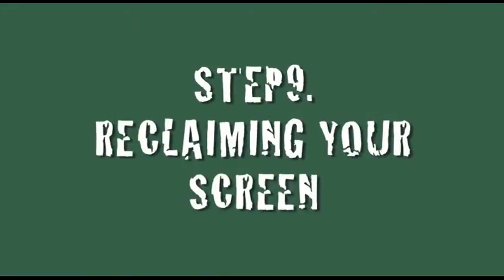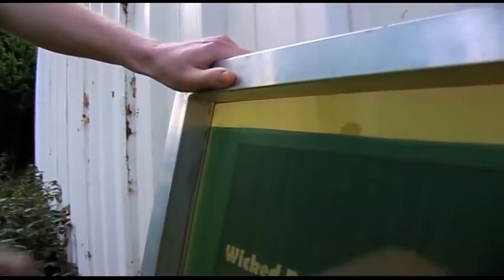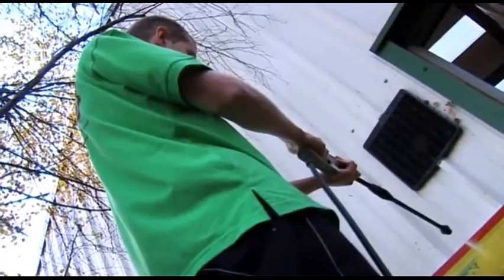To reclaim your screen back to its original state by removing the emulsion completely, you will need stencil strip, a screen cleaning brush, and a power washer. Wicked Printing Stuff stencil strip must be diluted 1 part stencil strip to 30 parts water. Remove the tape from your screen. Brush the stencil strip liberally onto both sides of your screen. You should see your emulsion breaking up at this point. If your screen is old or your emulsion stubborn, leave to stand for 1 minute or so and then hose down with your power washer. Cold water will be fine for this. You are now ready to degrease and start again.